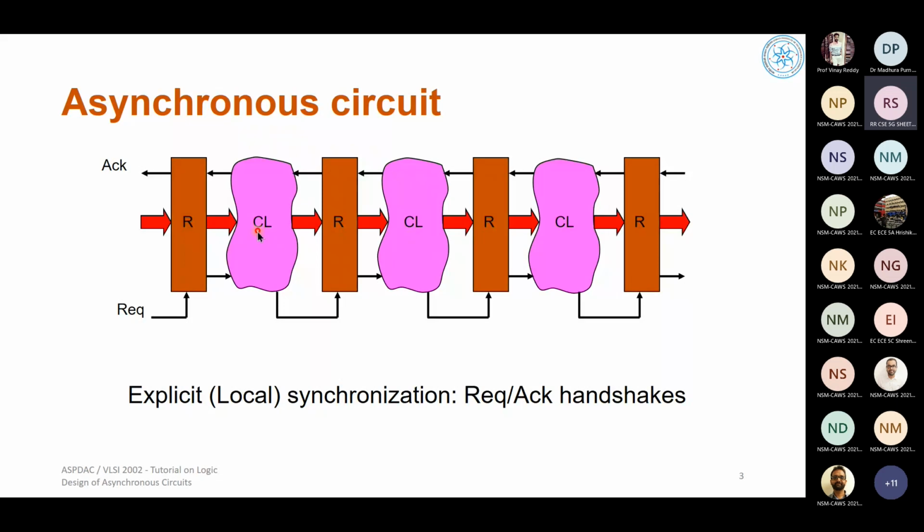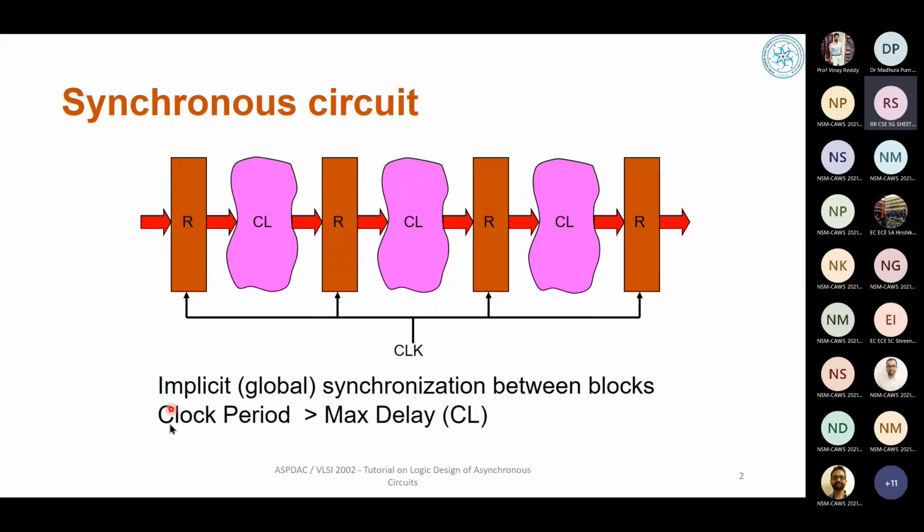Because in a synchronous design, in the previous slide that we saw, the clock period is fixed between the interstage buffers. So if the maximum clock delay comes from this stage, that prevents these other stages from running at their fastest timing, right? And so the max clock delay decides the clock period for the entire system, right?